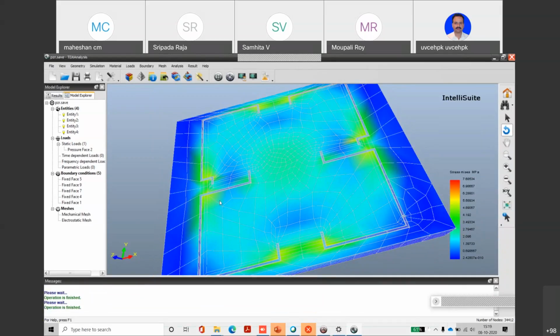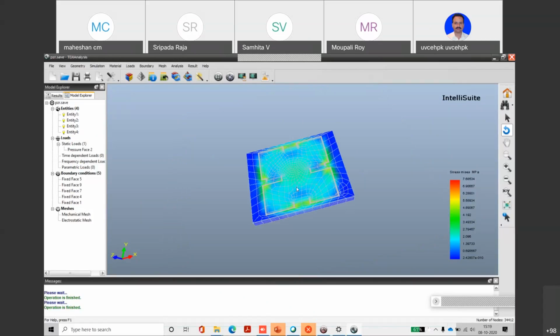So what we generally do is, say we have decided the resistivity value, we have decided the dimensions, everything we have decided, but we don't know where to mount the piezoresistors. We know the direction where to mount it, but where we have to mount exactly in the square geometry, if that is the case, then what we generally do is we create the device without the resistors, without the wires, and then we apply the pressure. We will see those regions which are showing maximum stress. In those regions, we mount the resistors. Okay, so that's the criteria that we follow.